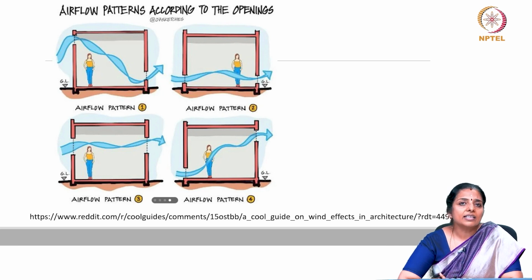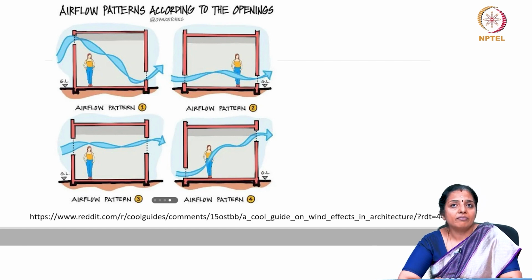An ideal case of fenestration position happens when windows are placed on two external walls with the door on one internal wall. If air is incident on any of the external windows, then the fenestration configuration not only ensures a good distribution of air but also has a larger outlet area than the inlet area.